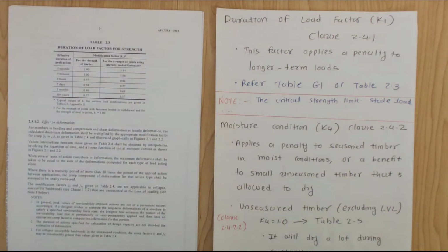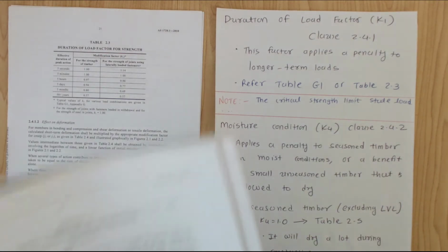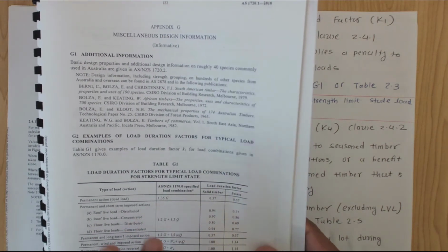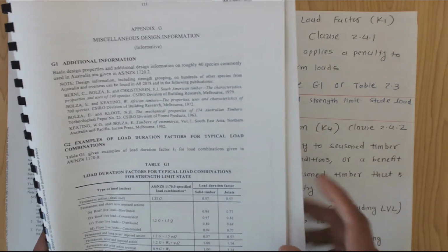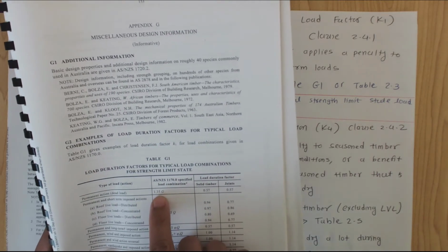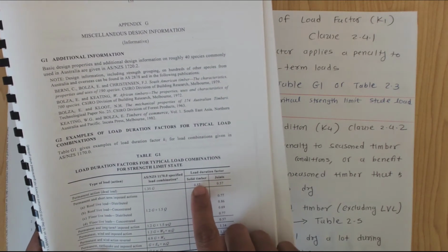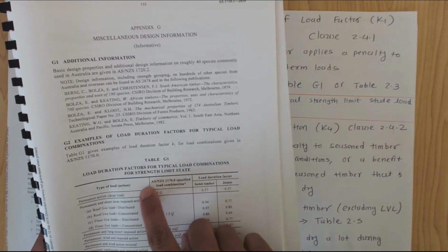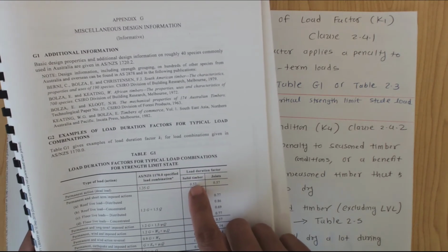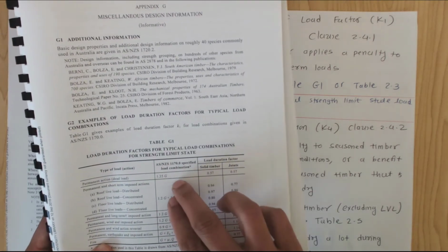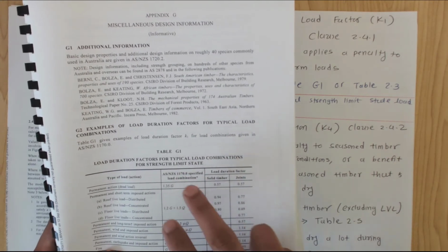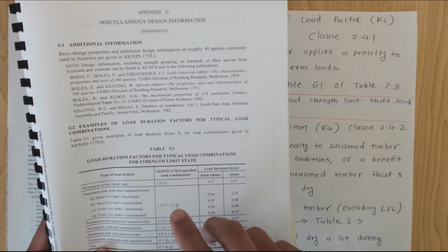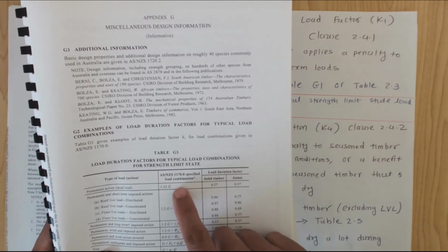Say if you are designing for steel members or concrete members, we work with, let's say, 1.2G and 1.5Q, which gives us the ultimate load. But here the K1 factors will be different for different combinations. For example, 1.35G, look at that K1 factor, 0.57. So in these timber designs you need to work out your design for 1.35G, 1.5G. All the load cases need to be checked independently, because your K1 value is different for different loading cases.